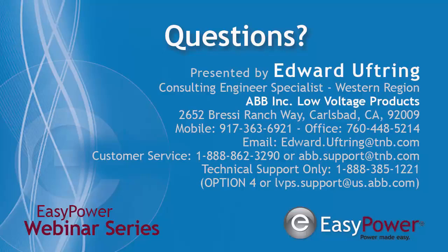Basically, in the test, you're racking out the device and you're taking it away from the service, but you're still allowing 120 volts so that the breaker acts normally. As far as when you're servicing the equipment, when you rack it out completely, the only thing you're seeing is 24 volts DC to power up the internal electronics of the breaker. There is nothing going on as a high power.